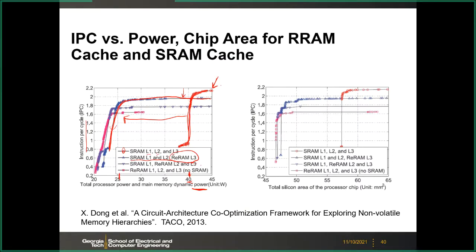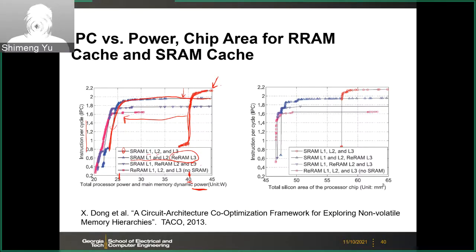This is because the workload is a mixed workload. Sometimes you do write-intensive applications, sometimes you do read-intensive applications, and sometimes the system is on standby, in the sleep mode. So those are the mixed applications. Especially during the standby, the SRAM consumes unnecessary power, right? But for the R1, you can power off that bank, or you can power off that cache. Your data is still there, right? So then you can greatly reduce the system level power.